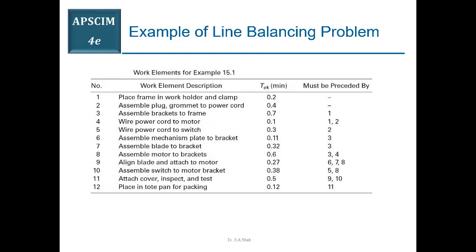So suppose you have a table and you want to generate the precedence diagram. So just look into the operations, and within those look for the independent operations that you can assign at any time without any reservation. So we have two operations that have no predecessors, which is operation number 1 and 2.